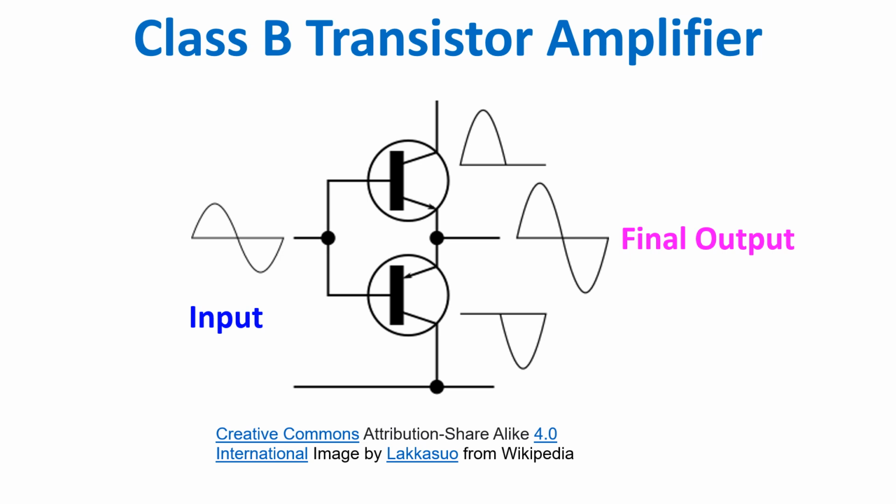As only half of the waveform is amplified, significant harmonic distortion is present in the output signal. In case of radio frequency amplifiers, this is taken care of by using tuned circuits in the output so that harmonics are shorted to the ground. This configuration is often used in linear amplifiers. At audio frequencies, two transistors can be used in a push-pull configuration.